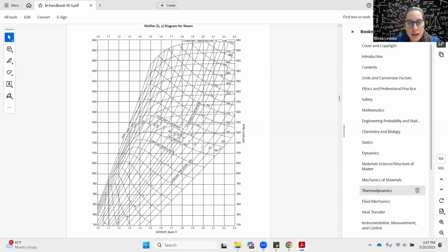So if you have a 5%, so the saturation line here is between the liquid and the gas. So down here, you would have something that is like really low enthalpy and really low entropy, and the percent of moisture increasing down here. And then at this point, there is 0 moisture, and then above that, you have gas. So all this is gas. All these are like 5%, 10%, 15%, so on, liquid.